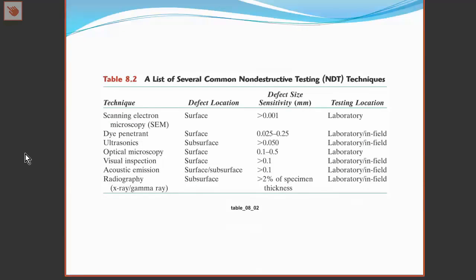So that brings us to the topic of different types of flaw detection methods. These are called non-destructive testing. Non-destructive testing is the ability to test a component without destroying it. Of course, one way to test a batch of samples is to take a few samples from the batch and test them to breaking point. This is expensive and is not always reliable. For instance, we may have just picked 2 good samples out of the batch. Non-destructive testing allows us to test the actual component that will be used in operation, and if it is not economically feasible to make more than one for testing, then non-destructive testing is the way to go.